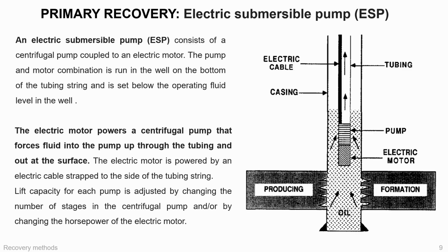Their performance can be adjusted by changing the number of pump stages or the motor horsepower. The main advantage of ESPs is their ability to handle large fluid volumes efficiently. However, they require electrical power and can be sensitive to gas handling in downhole conditions.